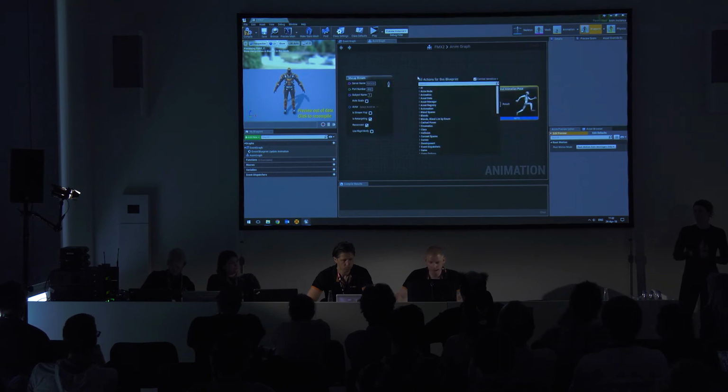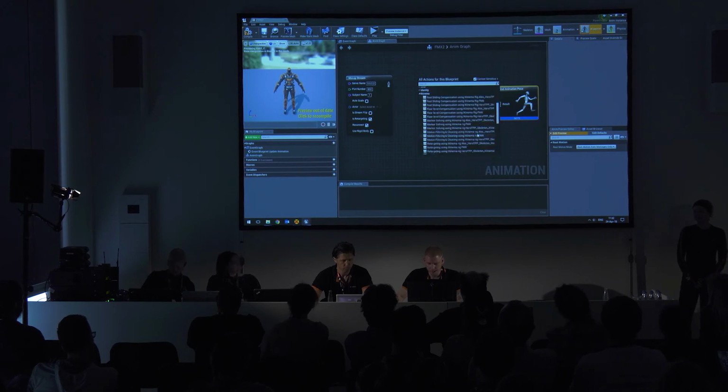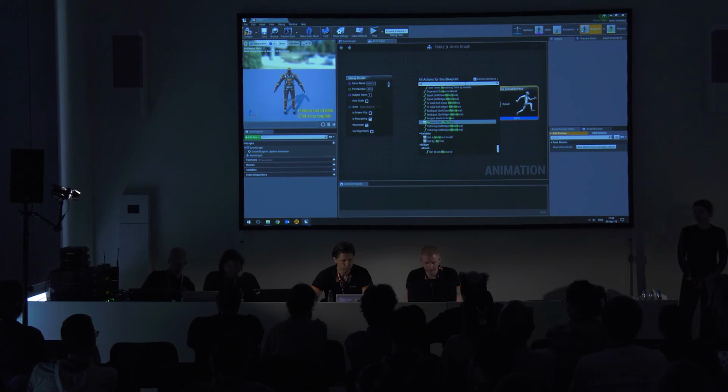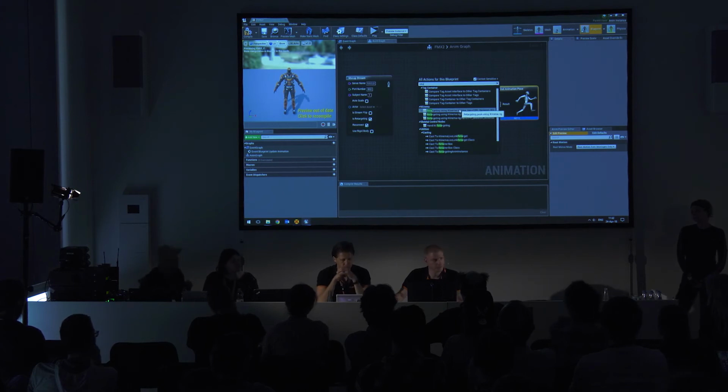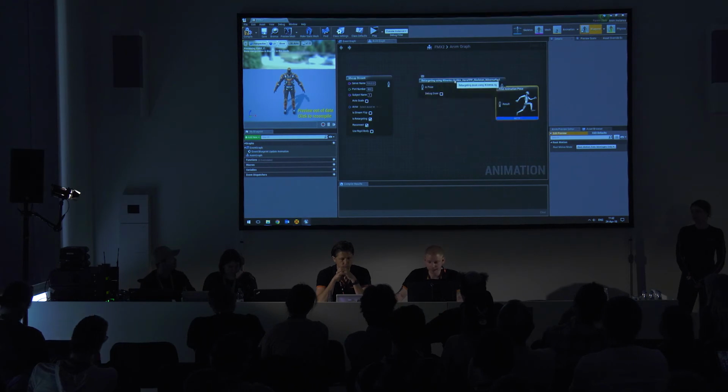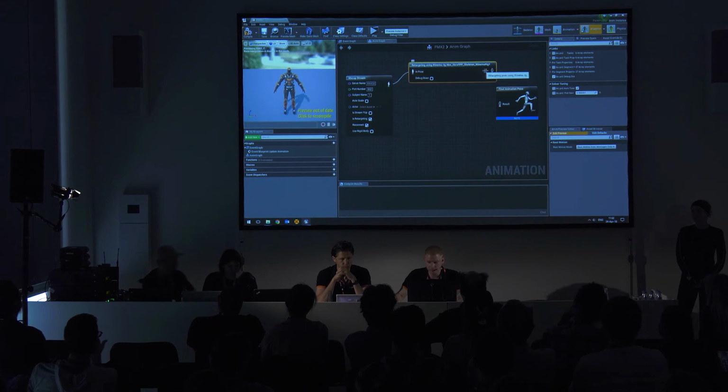What I need to do then is, again, right-click. I can either go to, I think, iKinema Live Action. No, it's iKinema. But what I can also do is retarget, maybe easier. So I want to retarget to the, now this is the one I've already set up, otherwise it would have been the FMX iKinema rig, which is here, which is not set up properly, so I'm going to pick this one. So I say that the mocap engine should retarget onto this iKinema rig that I just created. All I have to do then is link these up to be connected. So this is the final pose.